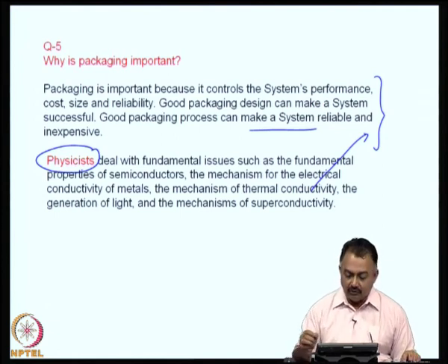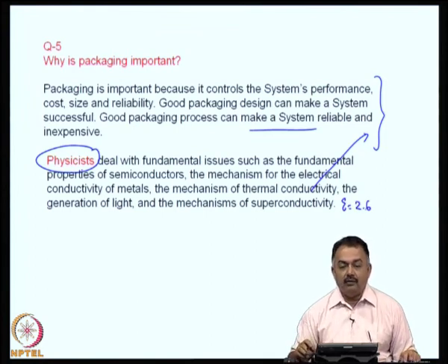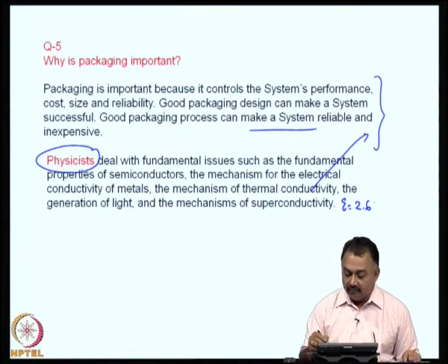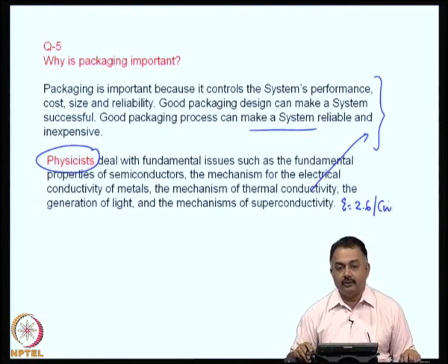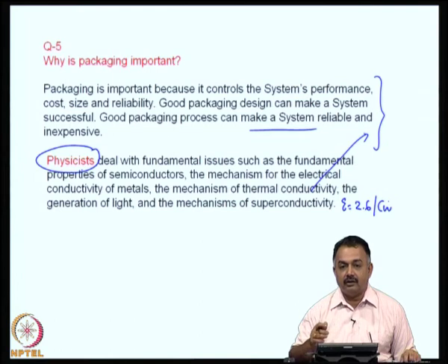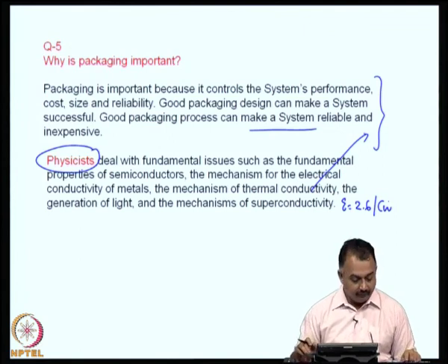If you want to use, let us say, a material with a dielectric constant of 2.6, can you really find out how good it is going to be in terms of electrical performance along with copper, and whether it is going to create a lot of crosstalk, noise and other parasitics in the electronics domain?